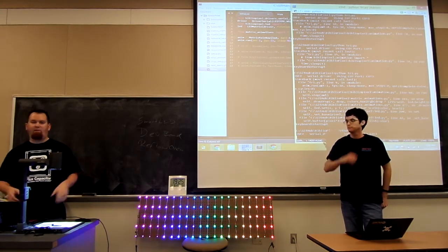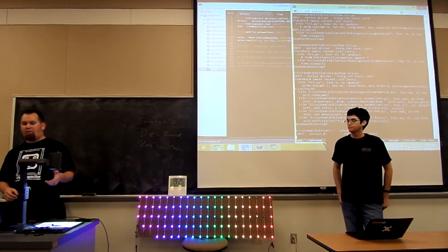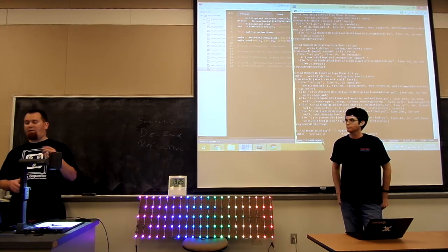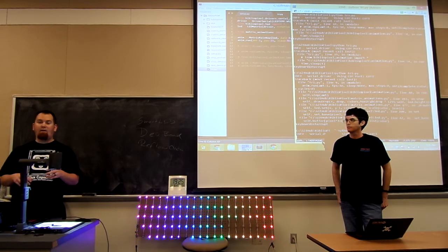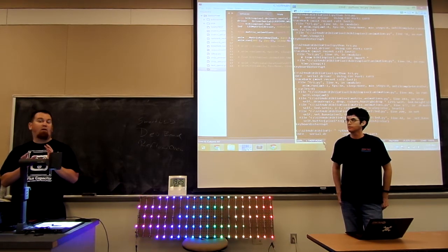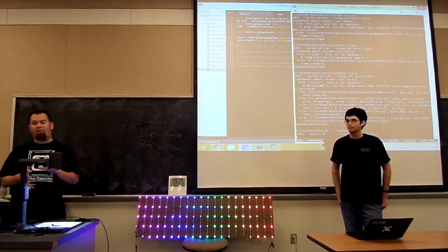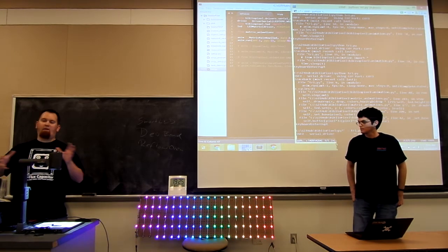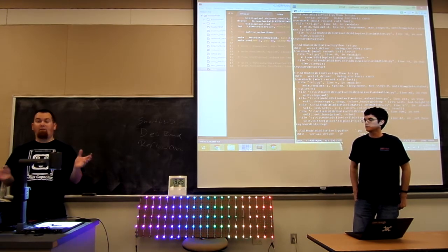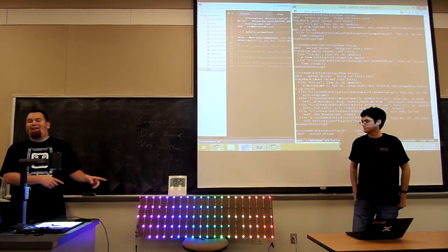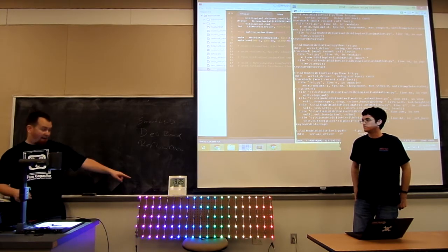then it latches. The WS2812 or the NeoPixels are even weirder because they've got this weird nanosecond timing that, since it's one pin, it's looking for a very specific 800 kilohertz data signal, and then when it gets a particular delay of a certain size, it stops. I don't know the details. That's why I made that. But that knows all the details.